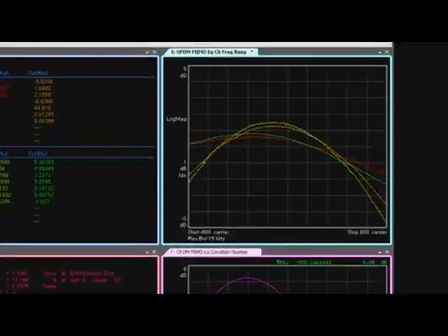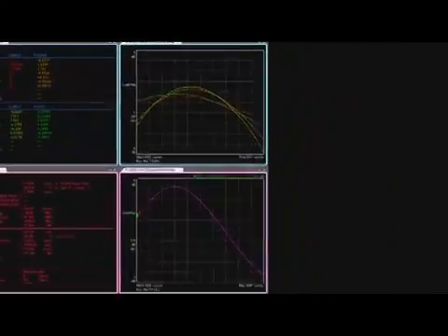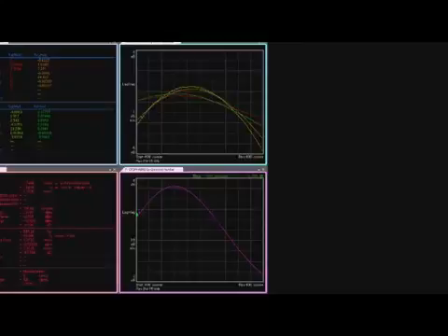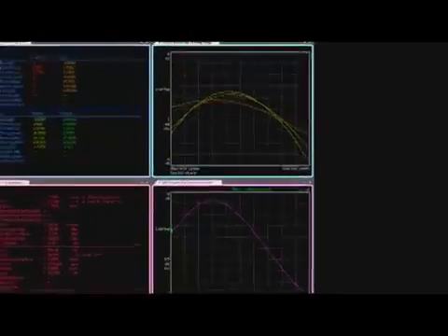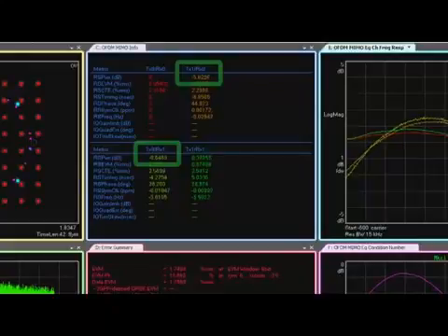The channel frequency response plot shown here displays the direct paths in red and green, while cross-channel gains are shown in orange and yellow. Comparing the frequency response with condition number, we can see that condition number is dominated by the amount of cross-coupling present in this signal. The MIMO information window shows the large amount of cross-coupling numerically here, but does not depict its frequency-dependent nature.